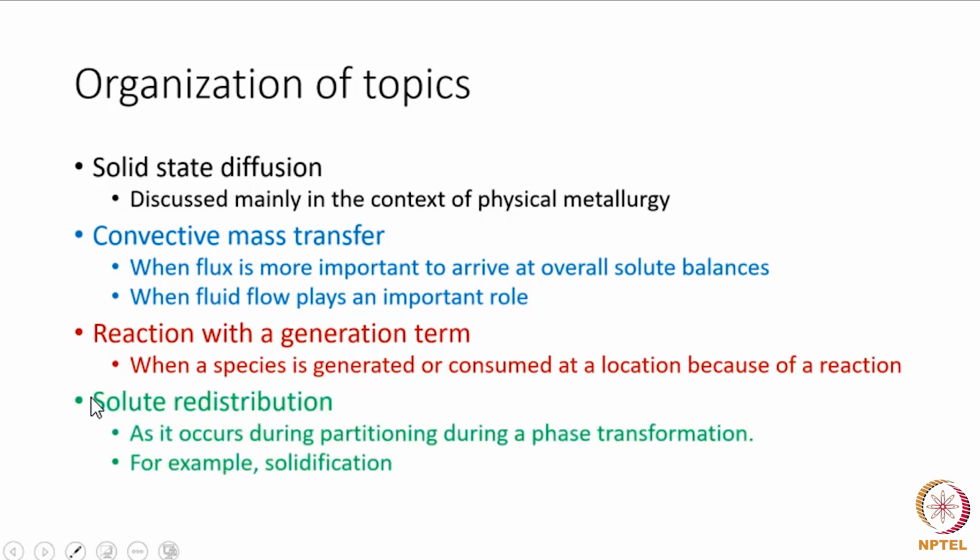We also have some concepts of solute redistribution that will be important. Usually this occurs during partitioning when a phase transformation is taking place. Examples of such situations are solidification. That is, the compositions of the phases that are in equilibrium are different across the interface, and that brings in a situation where the solute has to partition across the interface as the interface moves.